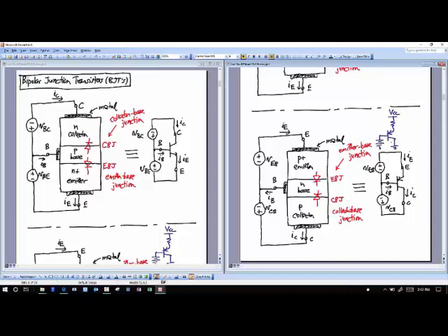Right? And so in this case, I'm interested in currents going down that way. Okay? And so for the PNP, that'll be IE, and that'll be IC, because currents always go from the high voltage to the low voltage. Right? And so in this case, for a PNP, this is the way it'll look, and that's how the voltages will look there. So that's why I take all the currents going down. You see what I'm doing in both cases? I'm taking all the currents going down in the NPN case and the PNP case. I'm just taking the currents going down is all I'm doing.